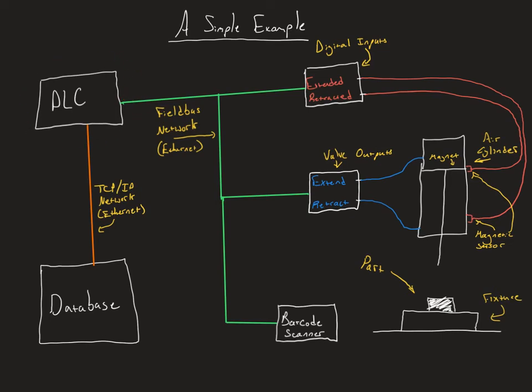And this is the typical way that a control system is implemented in the real world today: via PLC, field bus, valve manipulations that cause actuator movement, detection through instrumentation, input transmission across the field bus back to the PLC, and that closes the loop.